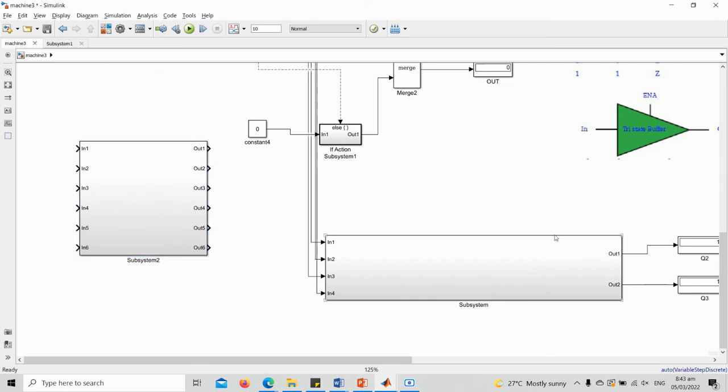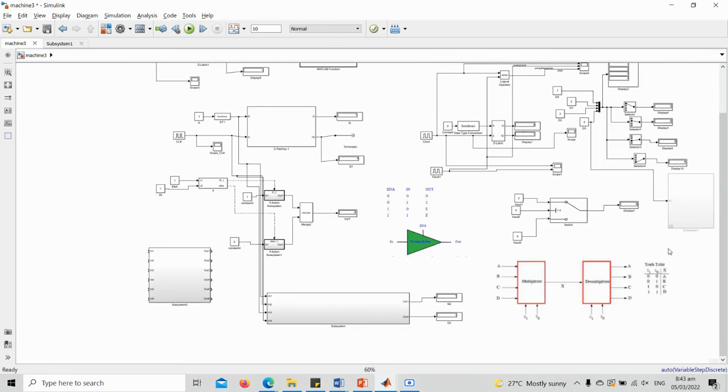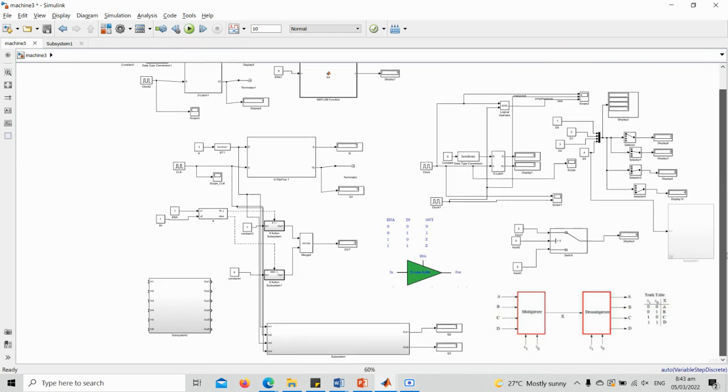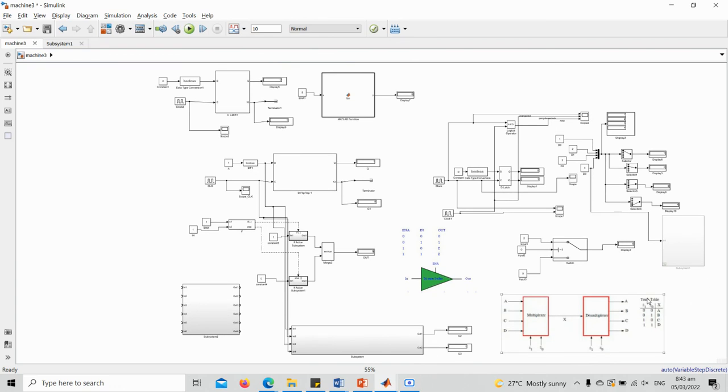All right. What else do I need to further explain? Multiplexer. Yes, multiplexer. All right. For the multiplexer, you just have to understand the truth table. So I suppose I already had given you an experiment on the multiplexer. For the multiplexer, as you can see, we have four inputs and we have two selectors. Okay, and then the output is connected to a demultiplexer, which requires two selectors again and four outputs.